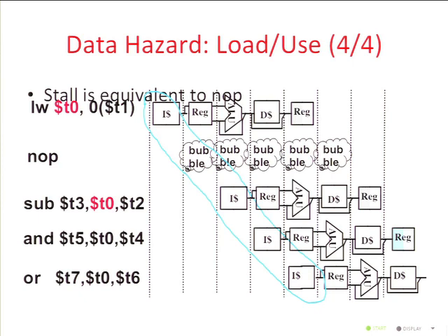For the interlock, there's no checking necessary because the hardware itself enforces it. And for the stuff we're talking about here, like you have to put a no-op in there, there's no check. If you get it wrong, there's going to be a bug. So it's that combination: the control does it for you, the hardware is going to do it for you, outside of the control. It's just going to stop the pipeline for a little bit. And, sorry, it's up to you, the compiler writer, to get it right.